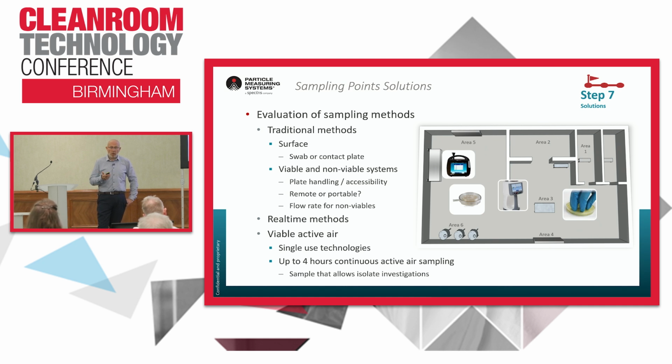The type of surface that we're trying to measure might dictate whether a swab or a contact plate is more appropriate, or the access to that surface. Viable and non-viable monitoring systems, so plate handling. I think Mike in his talk this morning talked about access and getting in to move these plates and to fit the plates, and that absolutely is an issue.